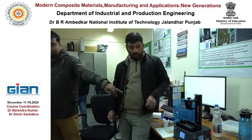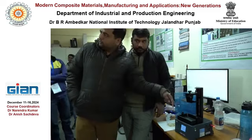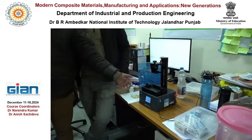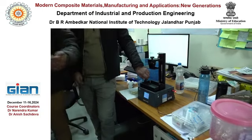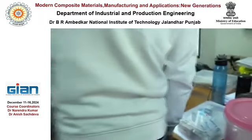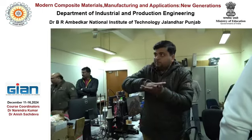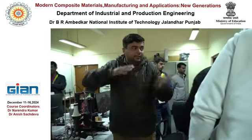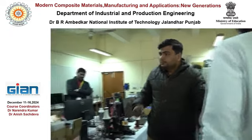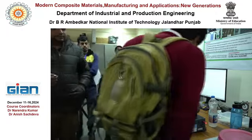Glass, right? You can come and see. We have transparent glass here, and you can also see the UV source. Please come here, one by one. You can see the working principle of the DLP process, right? We have the UV source at the bottom, then we have transparent glass at the bottom of the tank, then we have this build platform, right? So this is, I think, the idea behind the solidification. Okay.